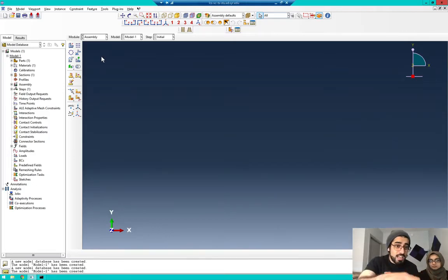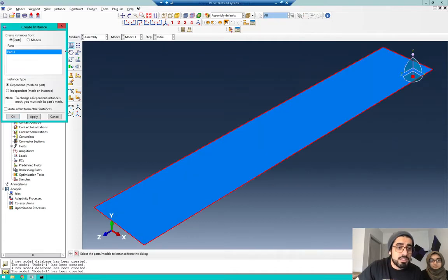I constructed now just the ruler because the whole model just has one ruler, okay? The oranges that we had are not parts, it's just loading. So here, I can draw one part, and then I draw the other part in Abaqus, and then in the assembly, I tell Abaqus how exactly they are assembled together. But here, how many parts do I have? Just one part. So I just go here, create an assembly, and create the instance of the assembly.